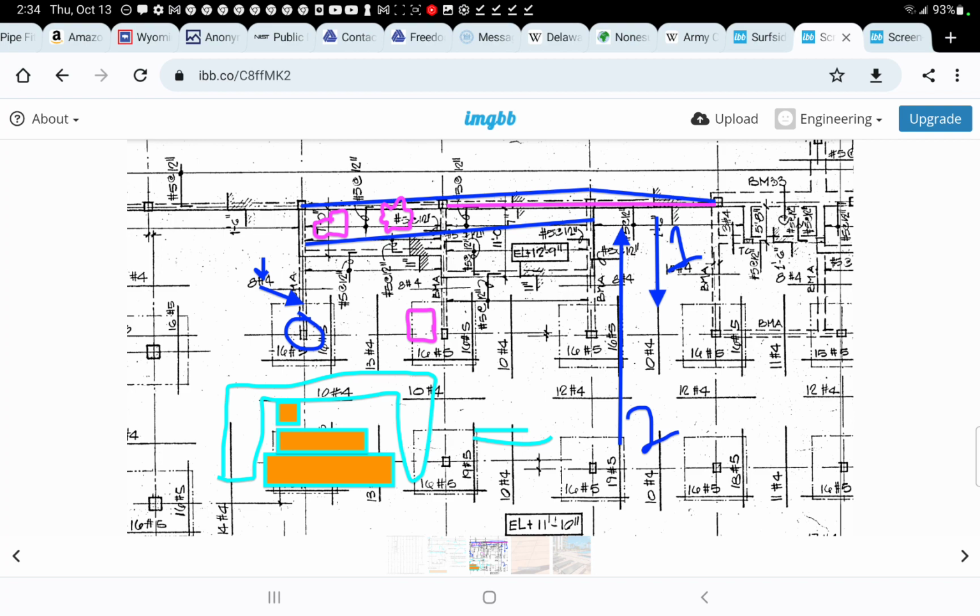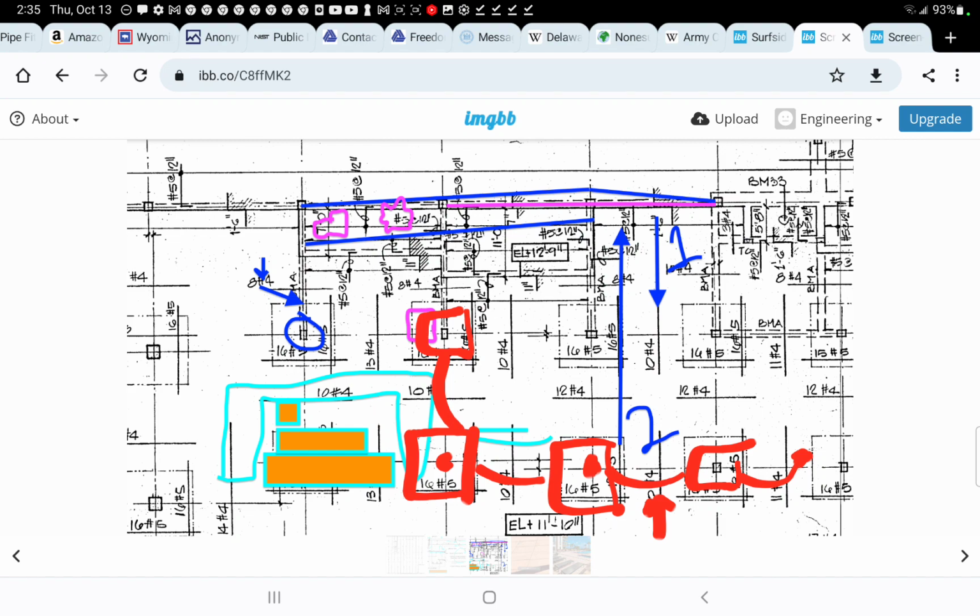Boy, I hope you're understanding this behavior of the deck, how it looks. So we've got critical shear zones just over top of the column edge of the overlay and the lower deck. We have our tributary areas, and this is back here even, right? Critical shear. I'm doing this little arch to help you understand this, the deflective zone. Over here would be the same, okay? This side would behave differently than this side. This is the BMA.